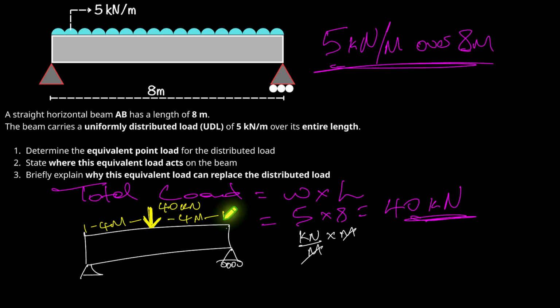So whenever you see a uniformly distributed load, just remember, multiply the load by the length to get the total force and place it at the center. Now in the next video, we'll look at what happens when the load only covers part of the beam, and that's where things get a bit more interesting.